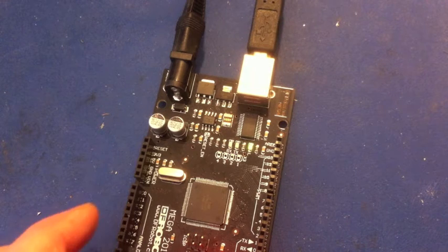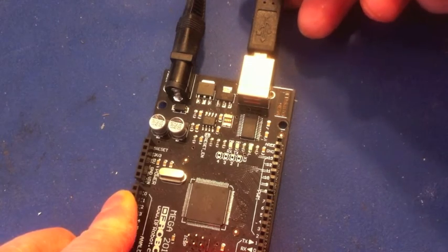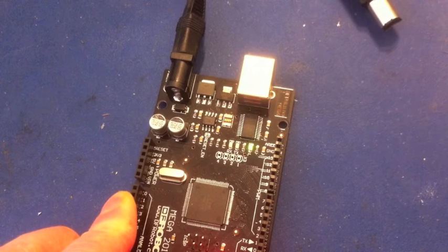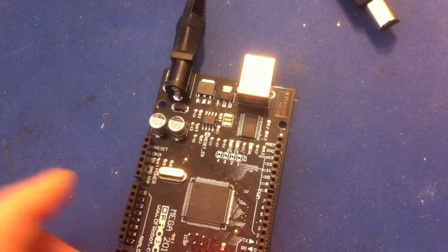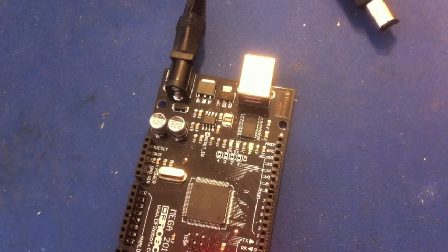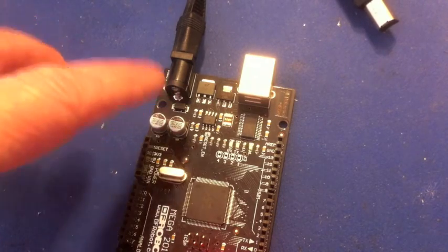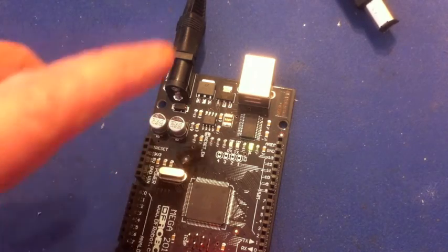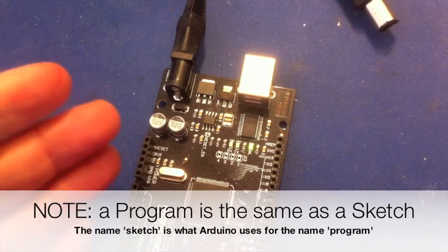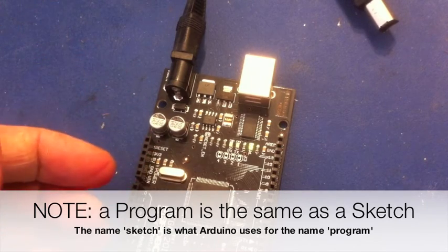So here's our Arduino board that we've sent the program over to. Notice if I pull out the actual USB cable, it won't make any difference. You can see once that program has been installed, it's still blinking. Now what's useful about that is you can place this Arduino board in a box or anything else. Later on, when you build more sophisticated projects, you can build this as part of the project. This little board can be slotted into the tin or the container if you're making a robot or something, because the program's now installed on this board. You don't need your computer anymore.